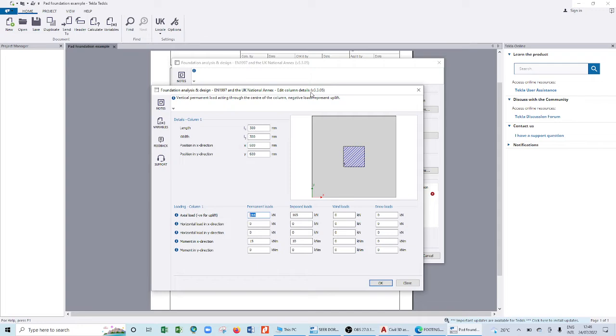Looking at this, we have always been in kilonewton, but what we had in our design was kilonewton per meter square. So we have to convert this to a unit. Half of 3 is 1.5, half of 2 is 1, the same thing outside. Half of 3 here is 1.5, this is 1. So the actual area that column carries is 2.5 by 2.5.